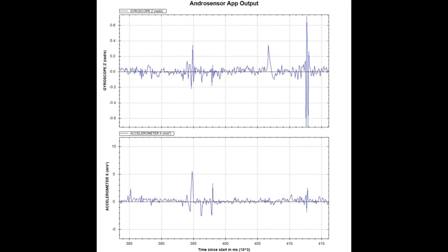So in this case, you can see in the accelerometer data, you get a 5 meter per second squared acceleration, and that's a pretty big yank. That's almost a half a G. So you're feeling that in your seat, so that's pretty uncomfortable. And then you see a couple more modifications or moves between 395 and 400.